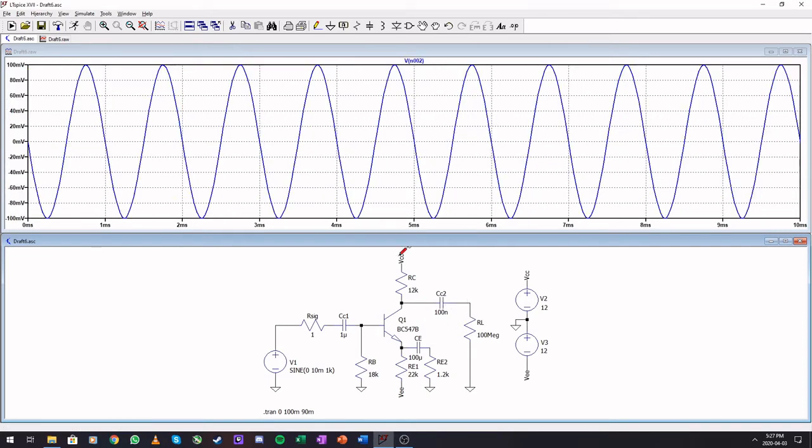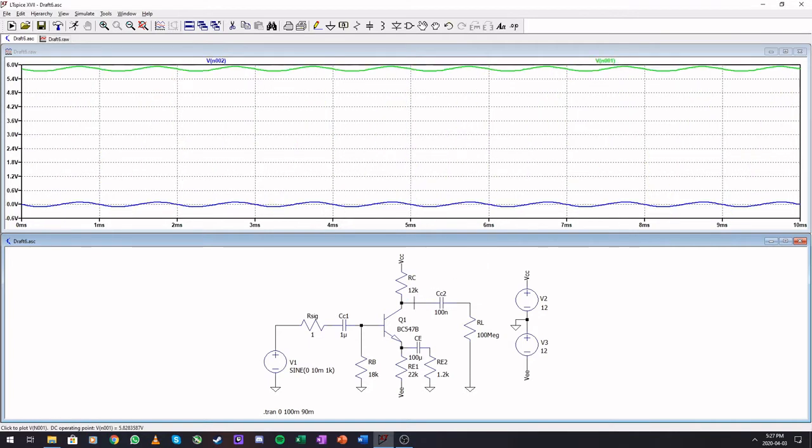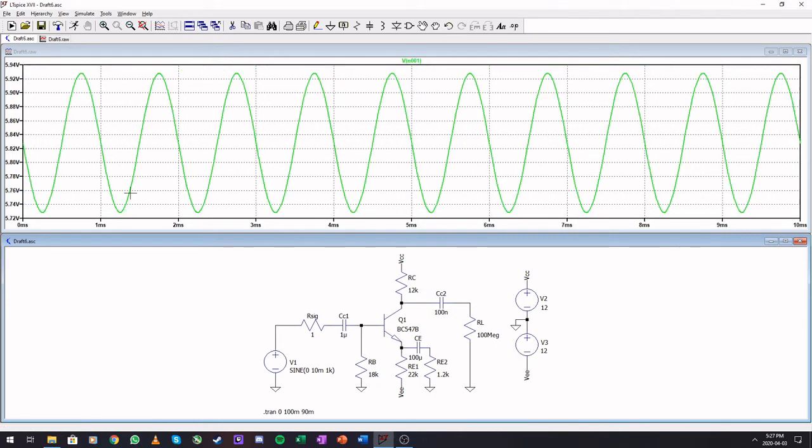So this is after a capacitor, so there is no DC. So this is a DC blocking capacitor, and if we take the measurement on the other side of this cap, we can see that we have a DC value added. By design, this should be roughly at 6 volts, because there should be 12 over here, or minus 0.7 volts sitting down there, and this should be in the middle of the two. So this should be around about at 6. Anyways,